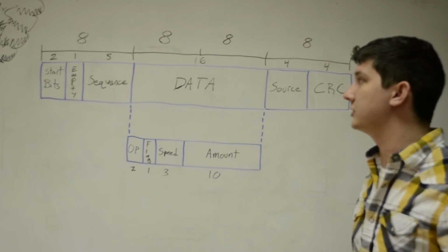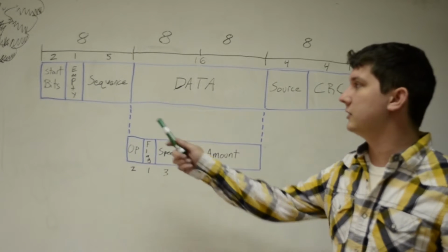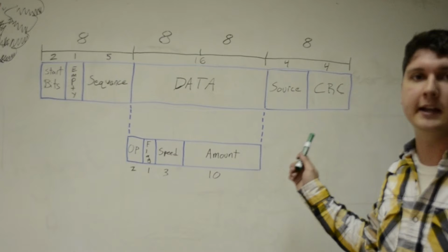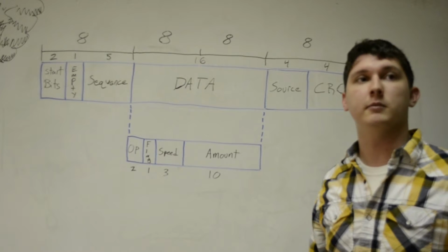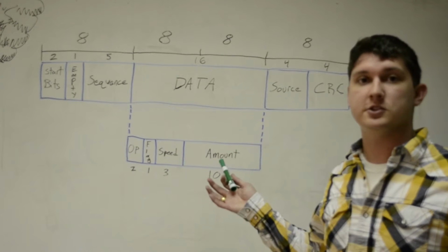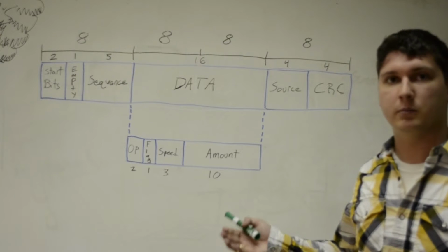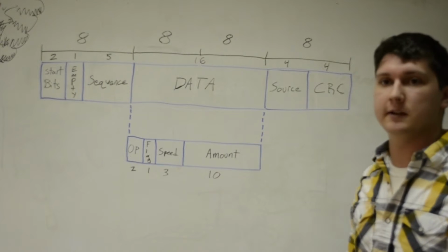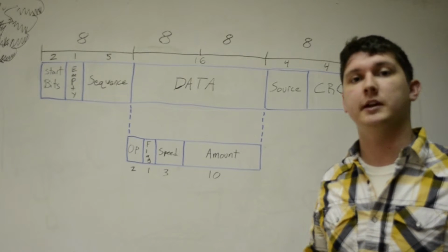So the CRC checksum actually gets us a lot of things, both internally and externally. CRC is a checksum that is calculated off of all the bits in the message, and we are able to check the CRC to see if the message format is valid. So we can throw out any invalid messages internally on the rover if a message is bad or comes over incorrectly. And when messages are being sent to the laptop, or the laptop sends messages to the rover, the laptop and the rover will both check the CRC to see if it's receiving a valid message. And if it isn't, it probably received a bad message or dropped a byte, in which case it will try to realign to the bytes coming in over serial.